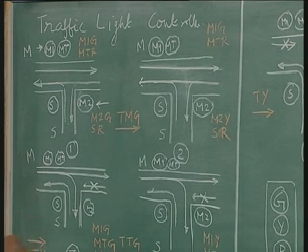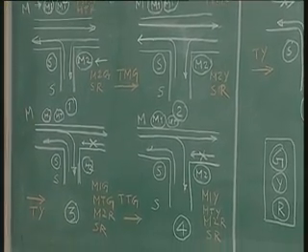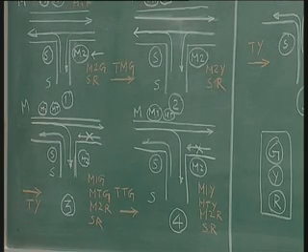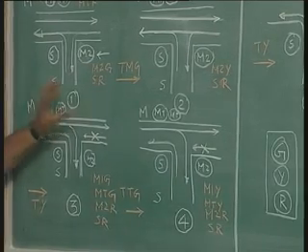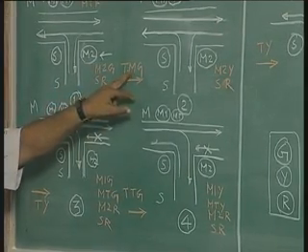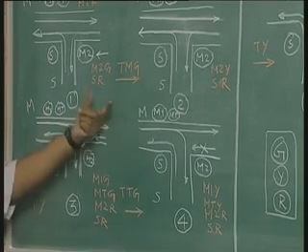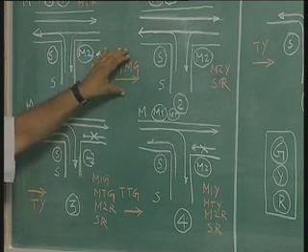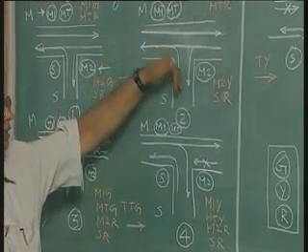At this point I can decide to wait for a traffic condition to be detected, or I can go for timing. To make this problem simpler, I am going to make it a time dependent change in lights rather than sensor dependent. The time for which the main is green is called TMG. After the time TMG has elapsed, we have to prepare to let the main street traffic go into the side street.